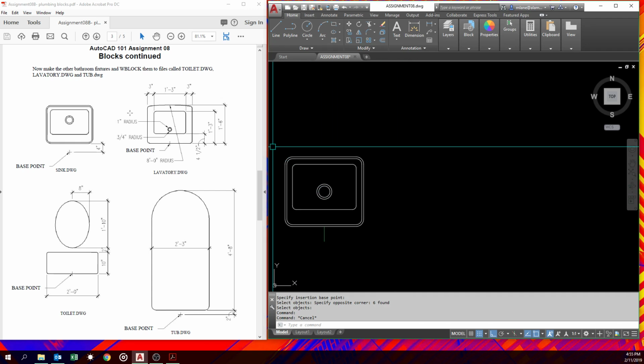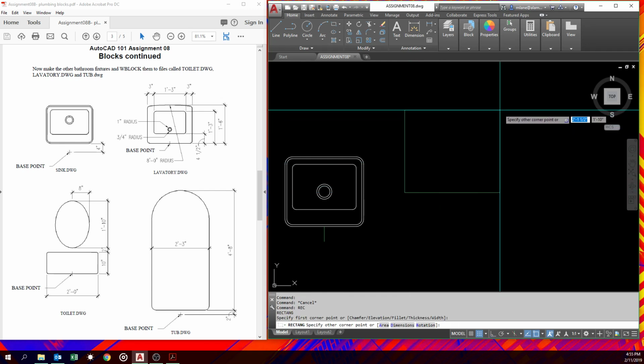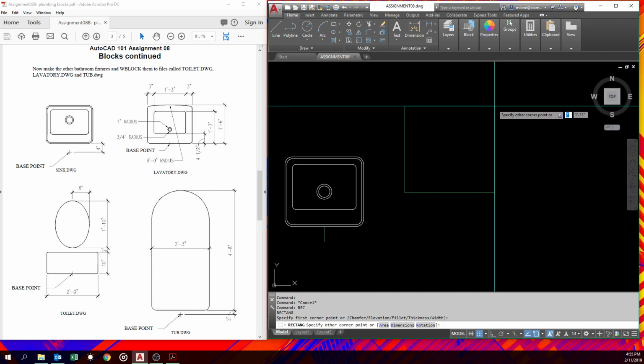This is a purchased item. So if you're ever going nuts trying to get everything right on a purchased item, you're wasting the company's time. You need to just get enough that reads right. Like in this case, we know that it's 1'6" by 1'9" wide. That's the really important thing. So we'll start with that. So don't draw more than you need to. 1'9", 1'6".